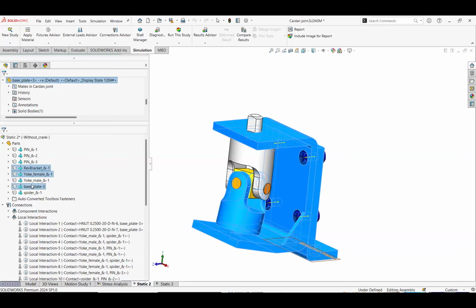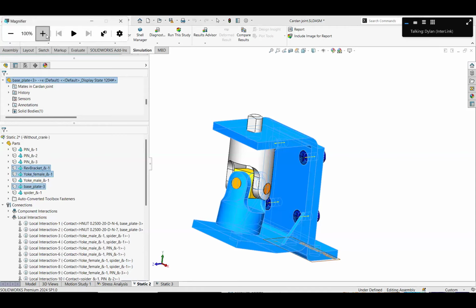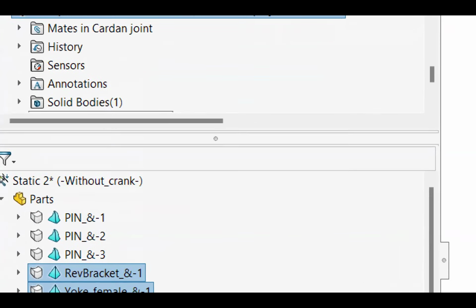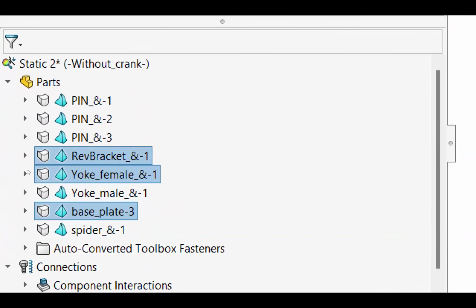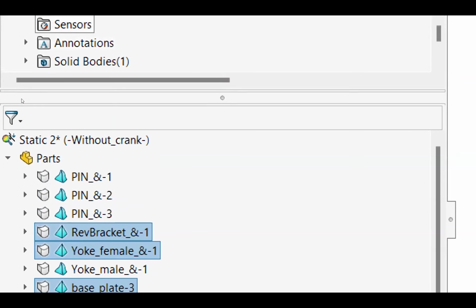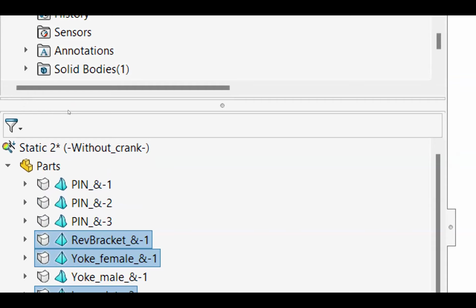I'm trying to remember how to zoom in. I think I need to turn on the magnifier capability. Oh, sweet. So you can see here that some of these individual elements now have straight edges. Those are your draft quality elements. The ones that have the squiggle tetrahedron are the high quality elements, indicating that there's a mid node or an inflection point there. But that's the idea. Let me zoom back out here.